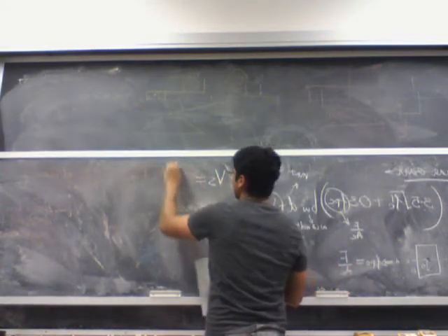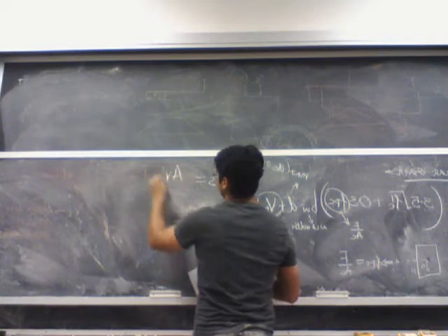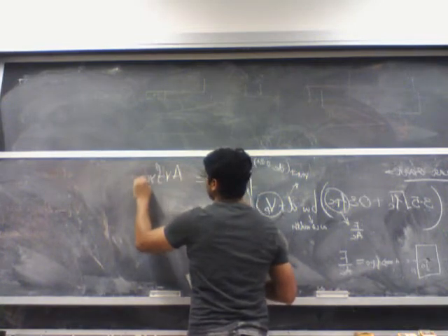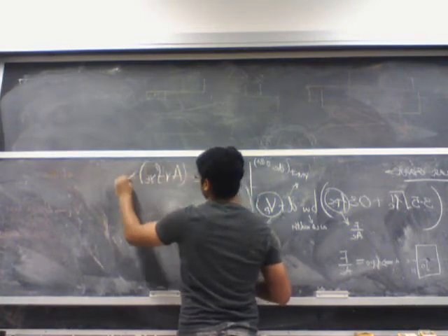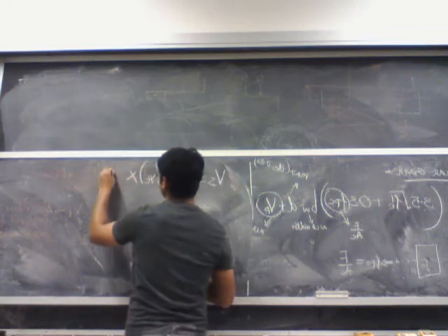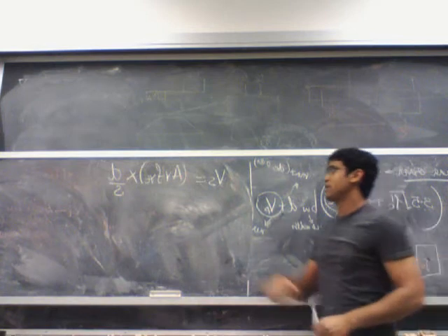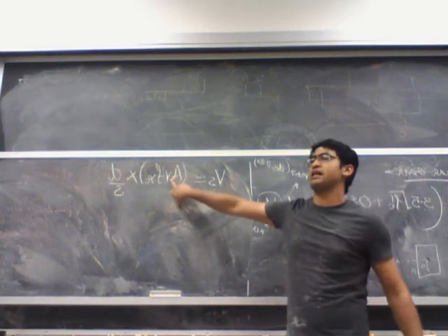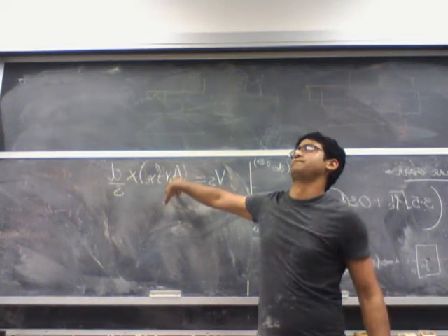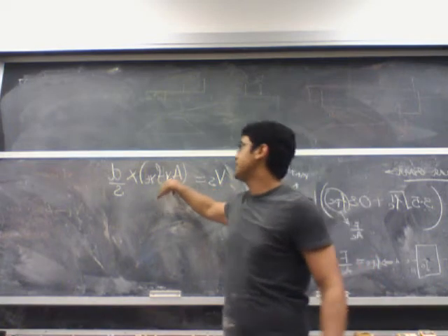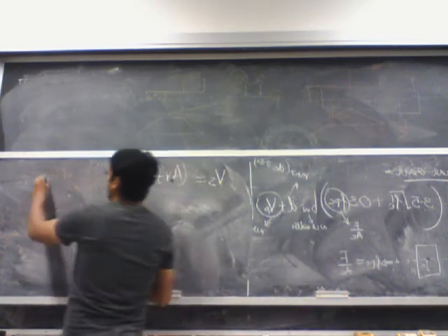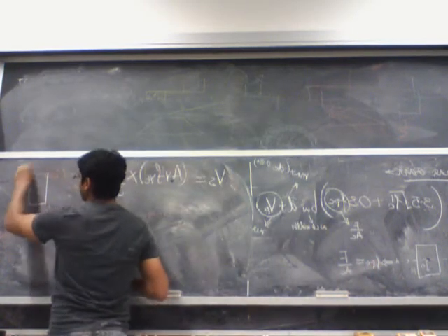Vs is given by Av fyt times d over s, where Av is the total area of one shear stirrup. So if you provide a shear stirrup which is a U shape,